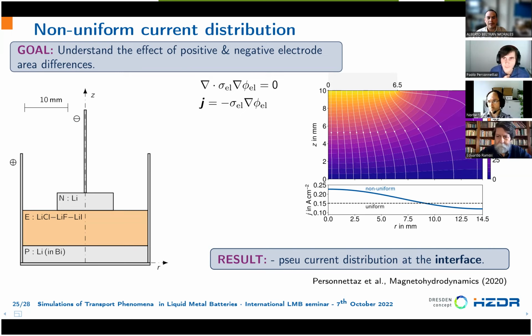And I mean, for some of the simulations, you use no slip condition, and then you consider a coupling between the layers, right? And you observe some variation of the solutal convection. So probably for a rotational flow or an electrovortex flow, these solutal convections will be affected, right?